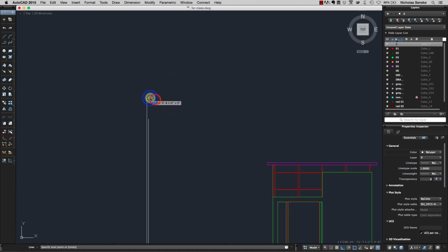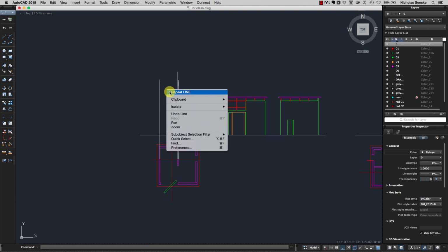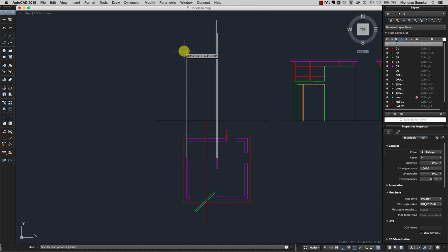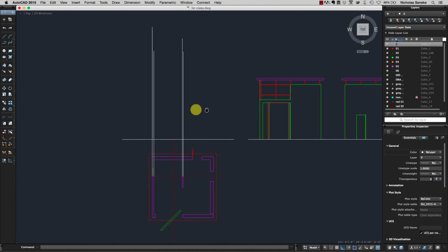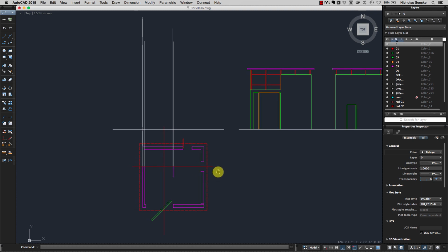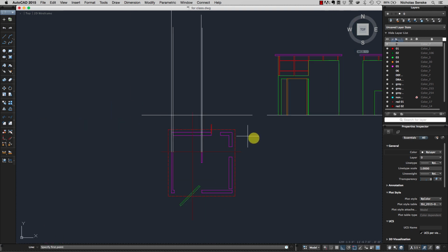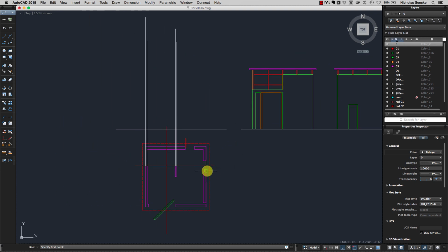I'm going to turn ortho on. And this doesn't have to be too careful because I'm going to be cutting these anyway, so I'm working kind of fast here. Okay, so I've got these two and they project up, and then I cut through this opening in the wall, and that's not actually something that I'm cutting, because I'm cutting right now. It's an opening, but then down here it's actually part of the space. So I'm going to project these lines anyway, but then I'm going to trim it later.